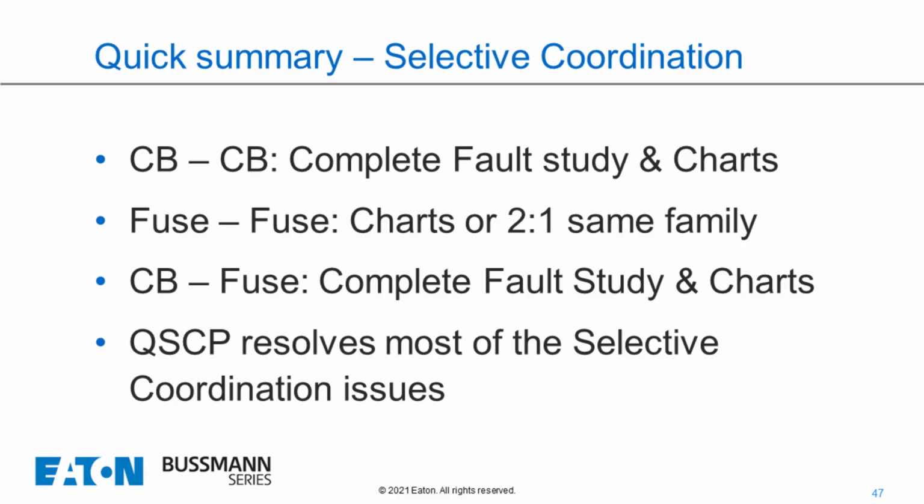And on our last example, we showed that if we put a 20 amp fuse feeding from a 100 amp fuse, and then upstream from that, we can basically use less expensive breakers as long as they match and look at the selective coordination as well as the interrupting rating and fault current.